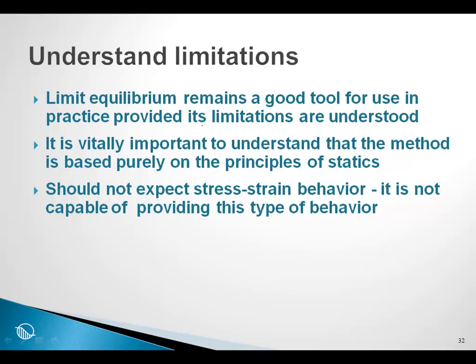It is vitally important to understand that the method is based purely on the principles of statics. There is no other physics included in the formulation. For example, we should not expect stress-strain behavior. It is not capable of providing this type of behavior because no stress-strain law has been included in the limit equilibrium formulation.